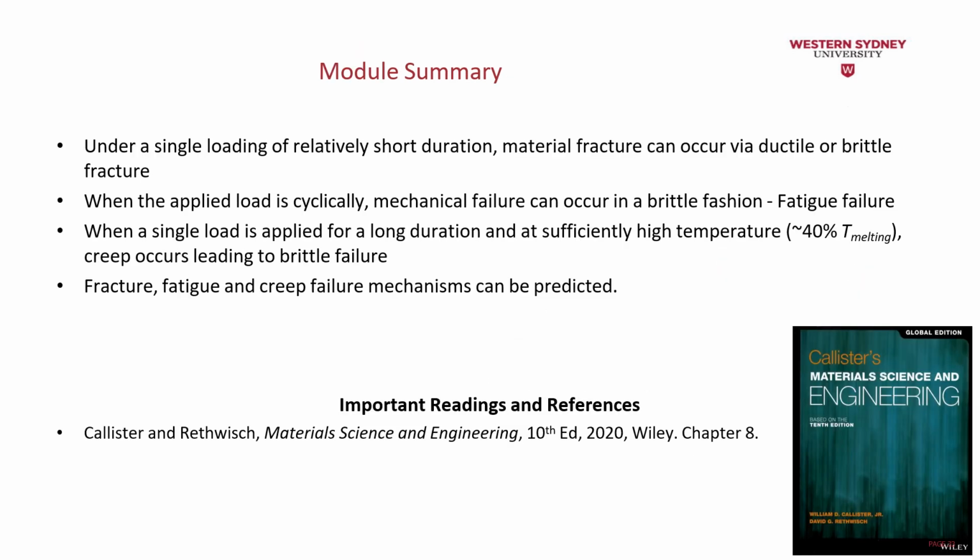Finally, the module summary is that under single loadings of relatively short duration, the material fracture can occur via ductile or brittle fracture. The second point is that when the applied load is cyclic, the mechanical failure can occur in a brittle fashion, which is called fatigue failure. The third point is that when a single load is applied for a long duration at a sufficiently high temperature, creep will occur, leading to a brittle failure. Finally, the fracture, fatigue, and creep failure mechanisms can be predicted.